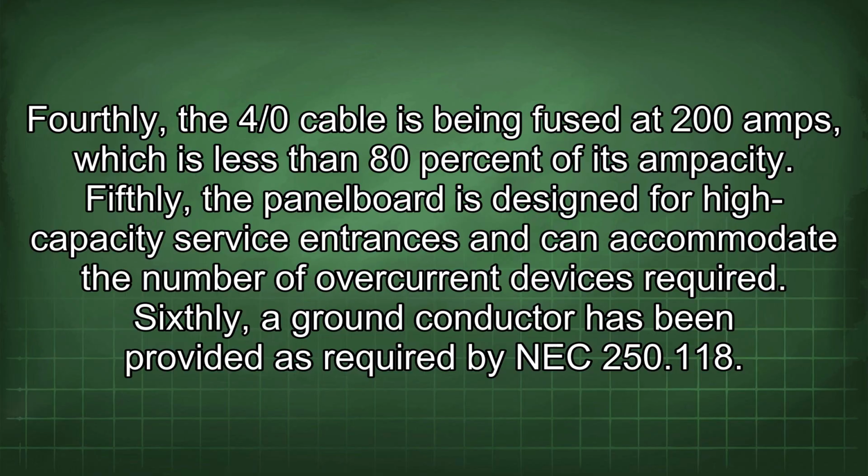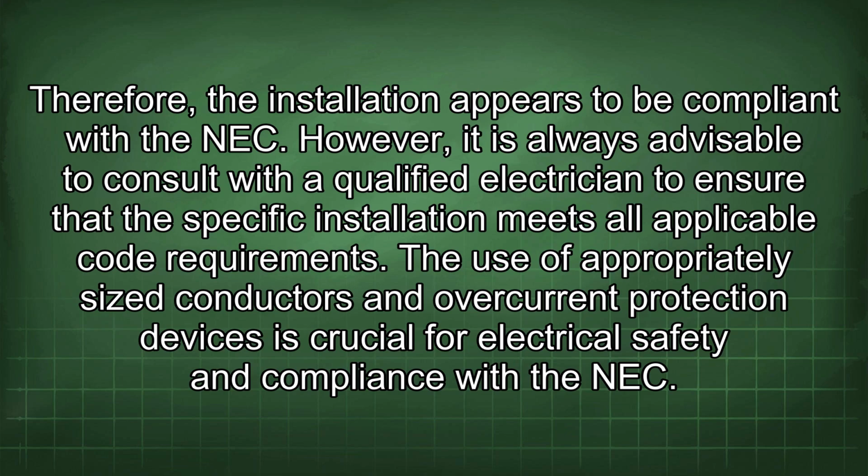Fifthly, the panel board is designed for high-capacity service entrances and can accommodate the number of overcurrent devices required. Sixthly, a ground conductor has been provided as required by NEC 250.118. Therefore, the installation appears to be compliant with the NEC.